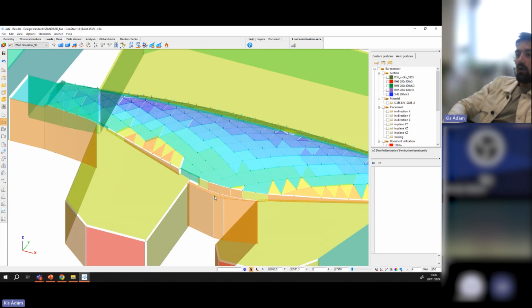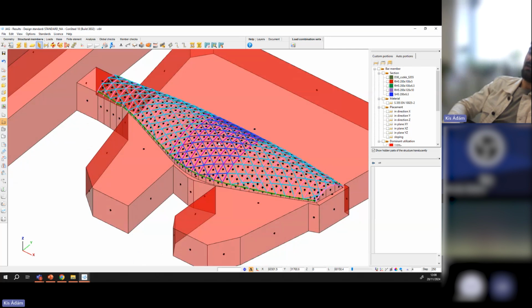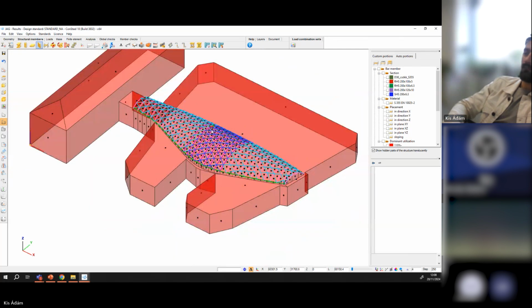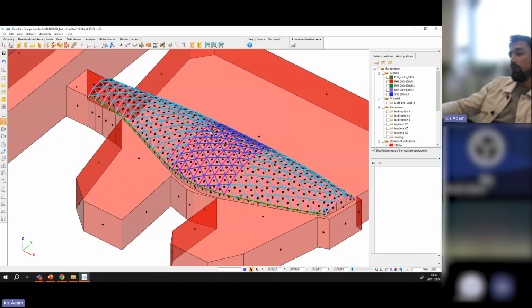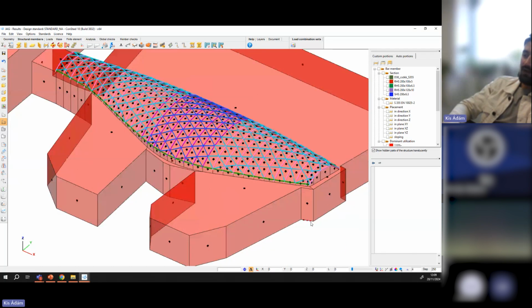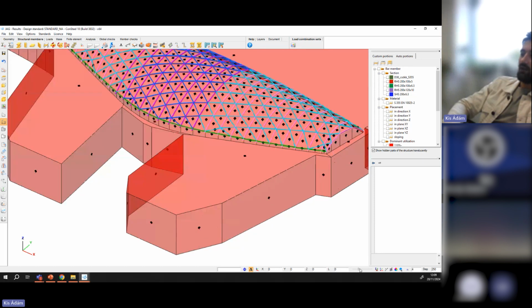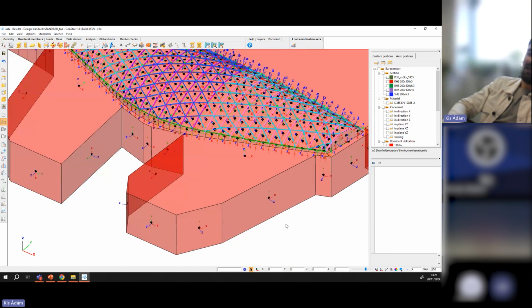Okay, so another thing regarding the structure is that when we have a closed building, it is always important to know which is the inner and which is the outer side of the building, which sounds quite straightforward, but from a modeling point of view, it is not always taken into consideration, because when we are drawing simulation surfaces, or in general load transfer surfaces, we are not always taking into consideration the local axis of these elements.